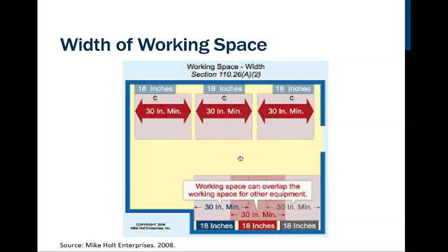And remember, a couple things have to happen here. We have to be able to open the doors in front of them as well. Now, a working space can overlap the working space of other equipment. This is per the NEC of 2008, which did not change in 11 or 14, so the slide is still valid.